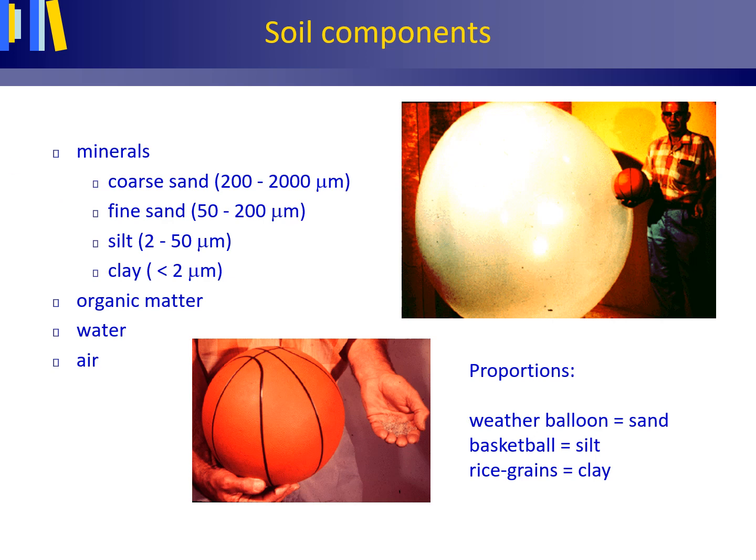If we compare the size of a sand grain to a weather balloon, then a silt particle has the size of a basketball and a clay particle the size of a rice grain. But watch out, clay has a laminated structure and not a granular structure, as this comparison may seem to suggest.